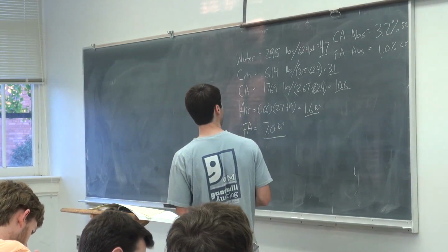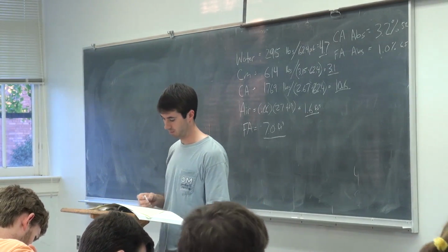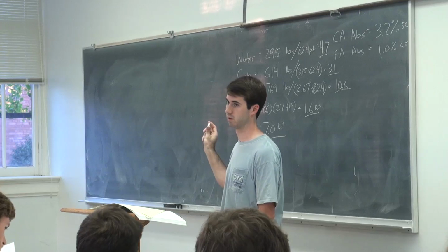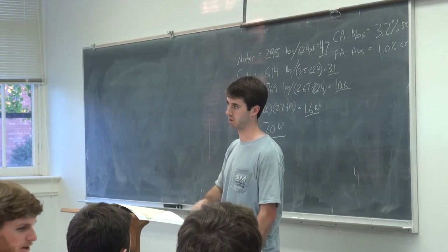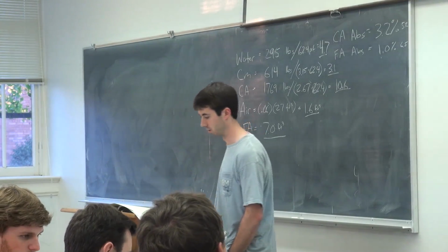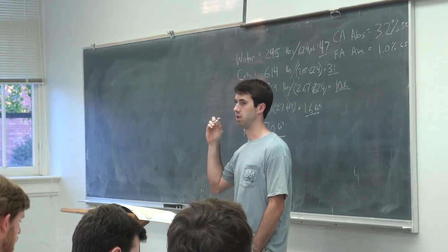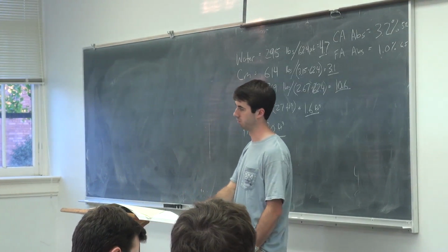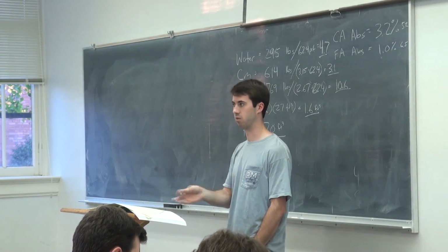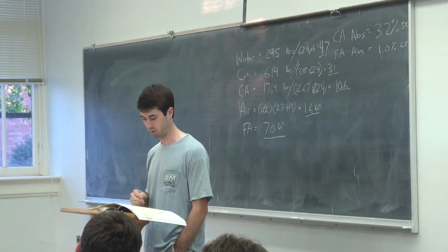So in that case, up to this point we're clear though, right? These are just the target values. This is assuming that aggregate absorbs nothing or has nothing to offer in terms of water. And so this is basically just the water that would lead to the water cement ratio of 0.48 that would lead to the strength we need. It's just enough water to react with the cement. But now we need to account for that one way or another.